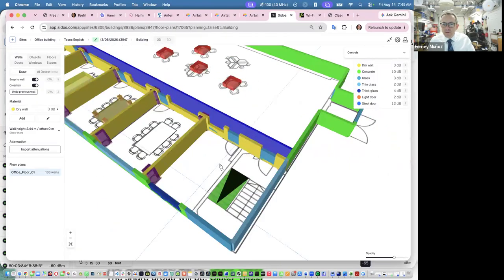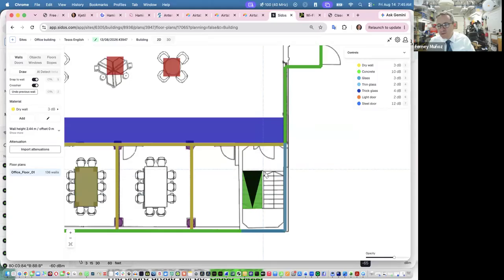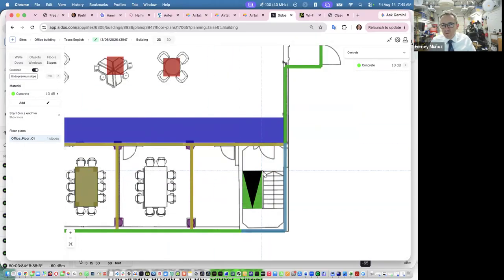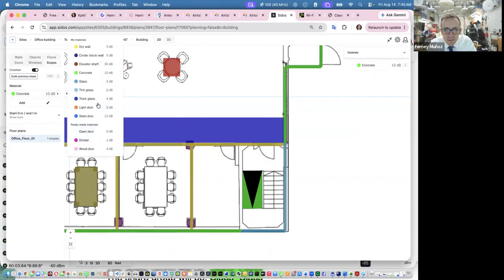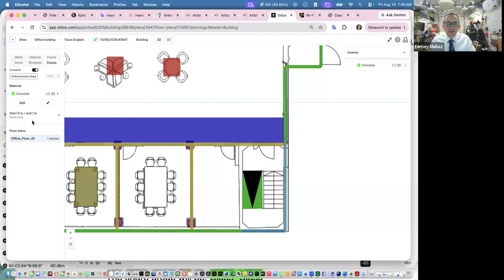Let's create the other slope. So if I went from, I forgot. Let's see, if I click there, oh, Control Z, then escape, and then go to slopes. So I went from here, bottom up. So then I go from here, slopes. Remember, since I had concrete, let's just change this to, oh, no, we're good. We're in concrete. So this one is not going to go from 0 to 1. The start height is going to start at 1 meter. And let's say go to 2.4.